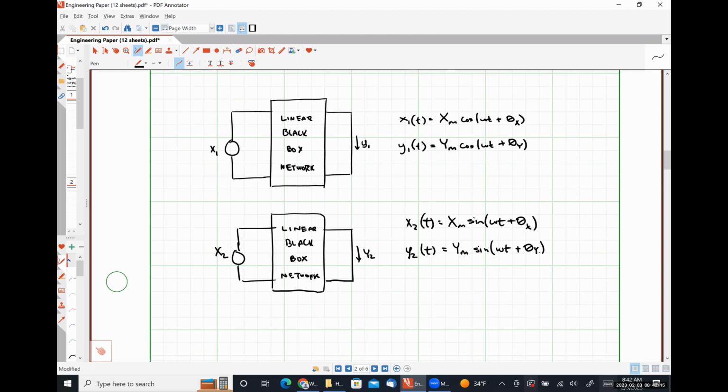How many of you guys remember the scaling property of linearity? We talked about it way back in like lecture 6, so 6 weeks ago or something at this point. Anybody recall talking about that stuff? The scaling property of linearity stated that if we scale our input by an arbitrary time invariant factor, our output scales by the same arbitrary time invariant factor.